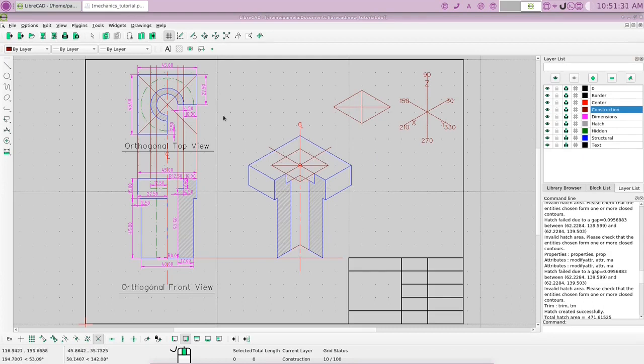Okay? So let's go to ellipse, because even though it's a circle, in an isometric view, it's going to look like an ellipse. Okay, so let's go to our structural layer. Let's choose an ellipse inscribed. Okay, choose that ellipse inscribed.